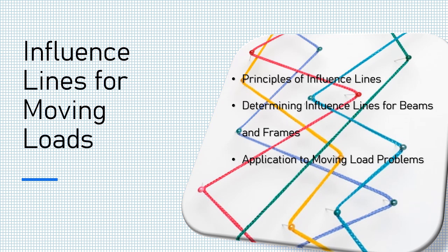8. Influence lines for moving loads. Principles of influence lines. Influence lines are a powerful tool used in structural analysis to determine how the internal forces, such as bending moments, shear forces, or axial forces, at a specific location in a structure change as a moving load passes over it. They are particularly useful in the analysis of structures subjected to moving loads, such as bridges and highways, where loads are not static but instead traverse along a structure.